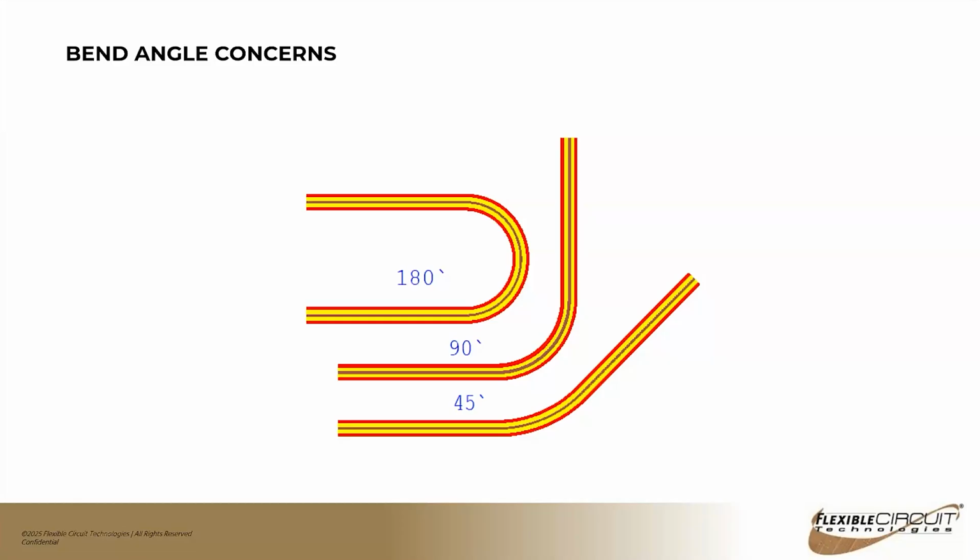Another thing to mention here is if a circuit is very thin or using very thin materials, to achieve some of these different radii, you actually have to bend the part further, as the nature of the material is that it really wants to relax back to its naturally flat state. So any of these radii or any radii in between are definitely possible. It just depends on what kind of tooling you use and how you're going to get to that finished state.